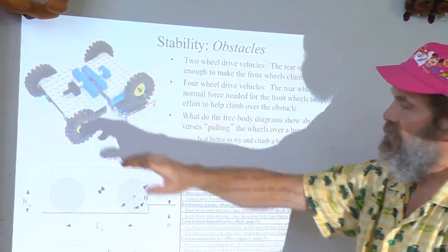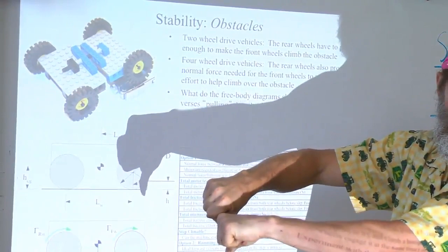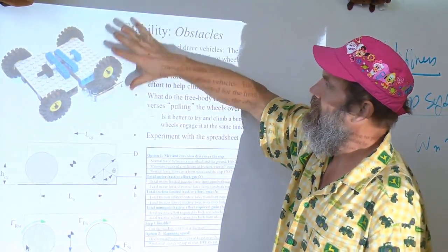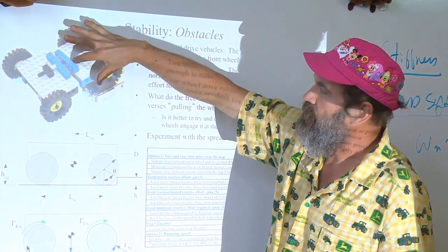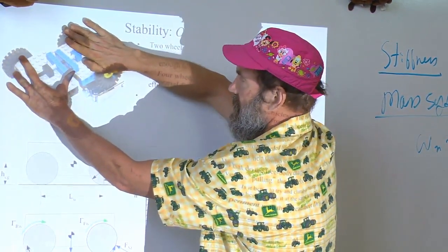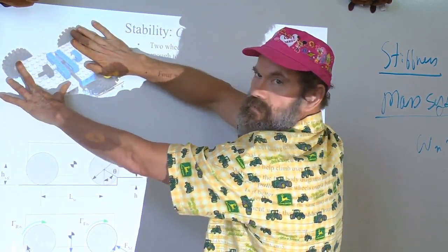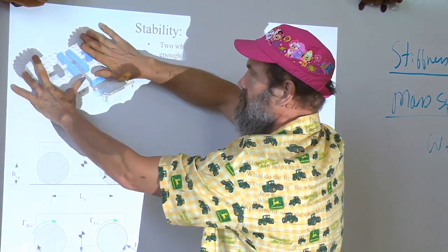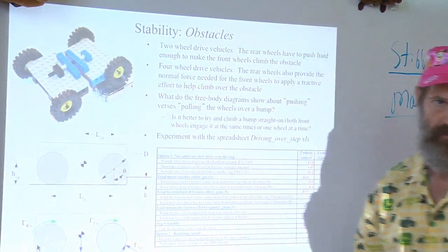The pivot is designed to be strong in bending, and now I can accommodate varying ground, and this pivot makes the vehicle emulate a three-wheeled vehicle, yet have the stability of a four-wheeled vehicle.